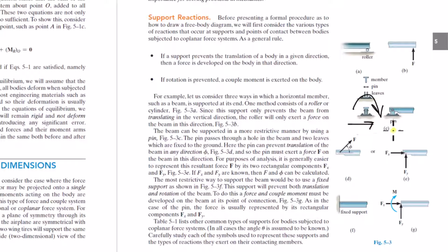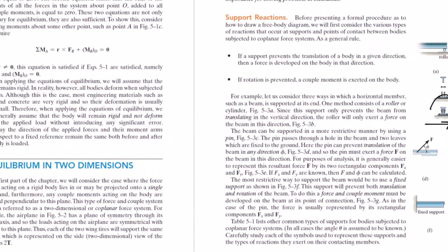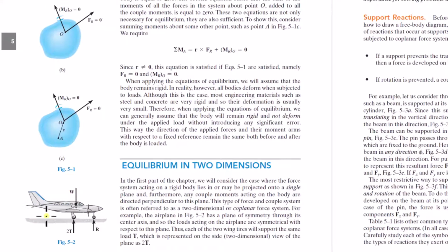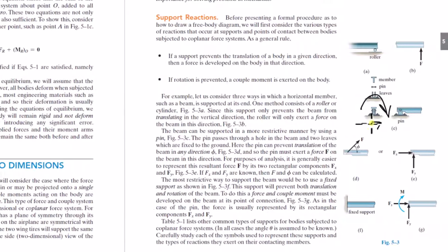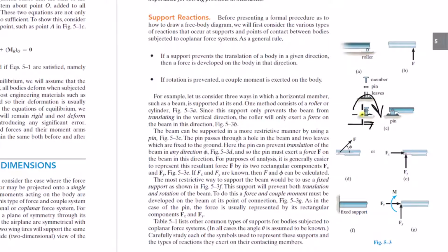That's why it's a 2D problem. That's why it's a planar problem, because even though technically there might be forces into or out of the page, I mean, technically, there always will be. There could be small gusts of wind into or out of the page. Those forces are negligible compared to the forces that are in the plane. If they aren't negligible, then this connection is wrong. You need a 3D connection.